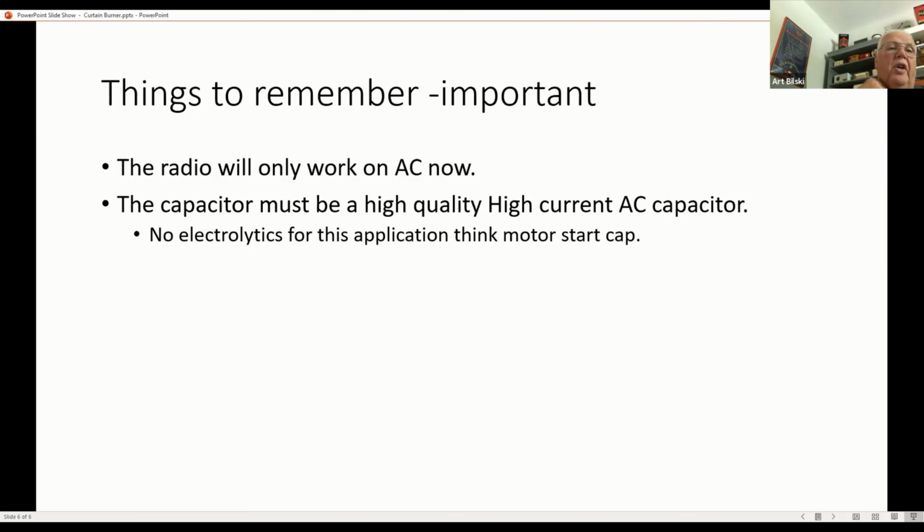Hey, Bill, where do you find the AC capacitors? You actually can find them places like Mouser, and the suggestion was actually Allied Industrial. You know, their industrial division still exists in some place in the world. But you can find those high value capacitors. They're really like big Mylar caps, but they are available. You can also find motor start capacitors from HVAC supply houses. I've been told that ceiling fan motors often use, like, a 7 microfarad motor start. Which might be just the one you need.